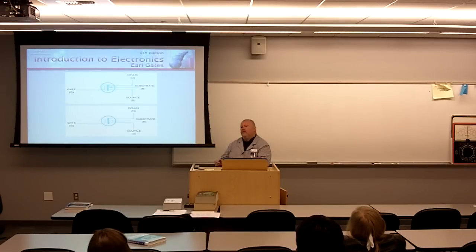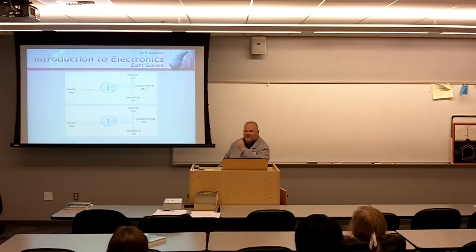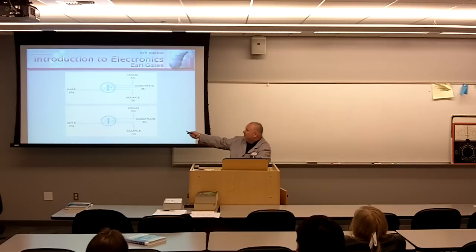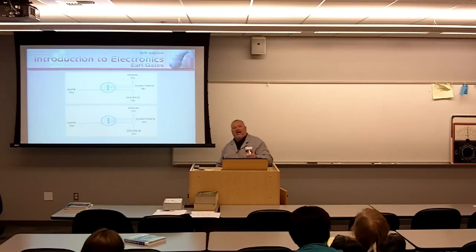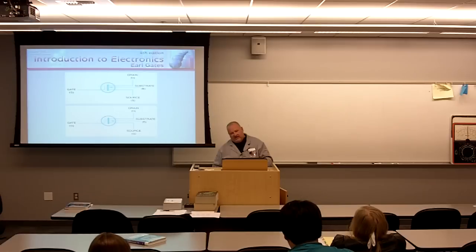The big thing I want you to realize on the schematic symbol is generally these look like N-channel JFETs, P-channel JFETs, except the gate here is not touching. That means it's electrically isolated. So therefore you know that this is going to be a MOS, metal oxide semiconductor, field effect transistor, MOSFET.